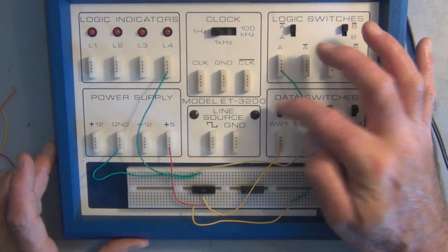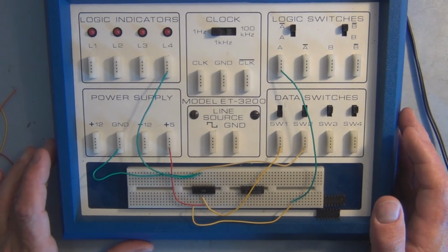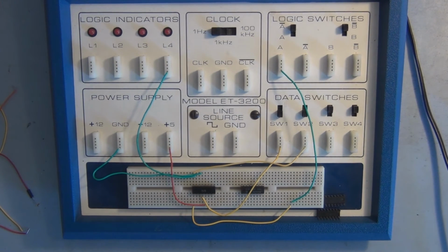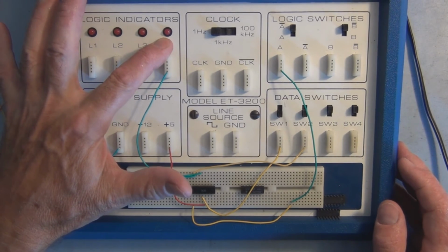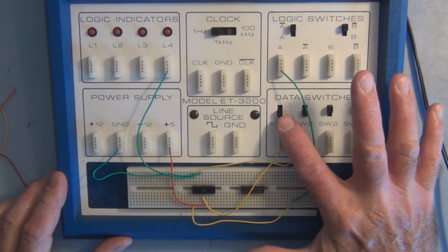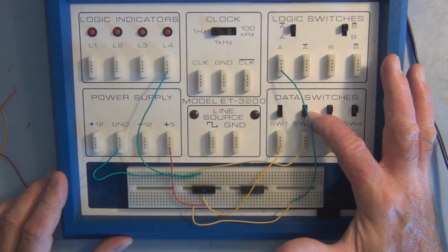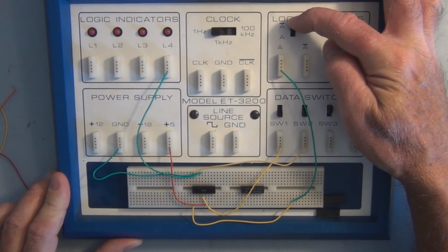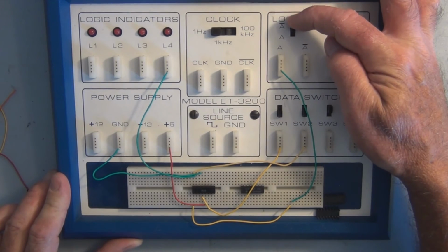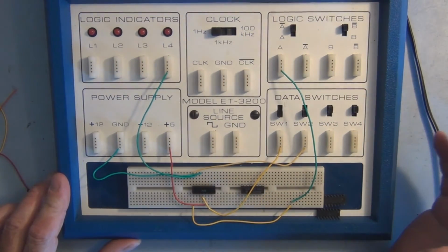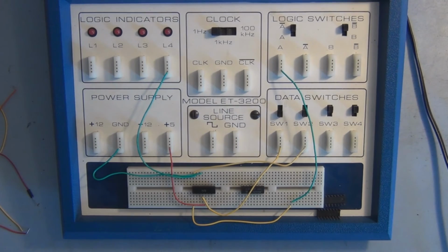Again, this is exactly like a Set-Clear flip-flop, except with the added benefit of a toggle mode of operation when J and K are both set to 1. So here we have 0 on the output. Q is equal to 0. And we have J equal to 0 and K equal to 0. And if we trigger the falling edge of a clock pulse, nothing happens. So we have a 0 and a 0, which is a no change condition.